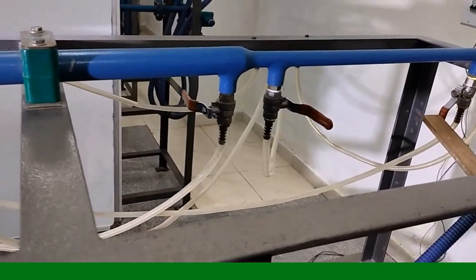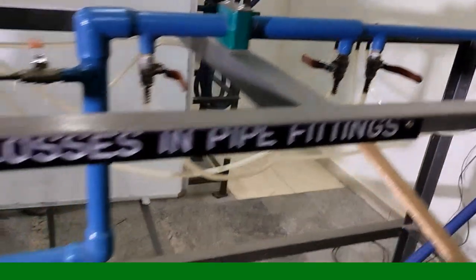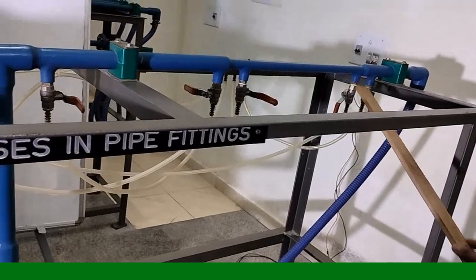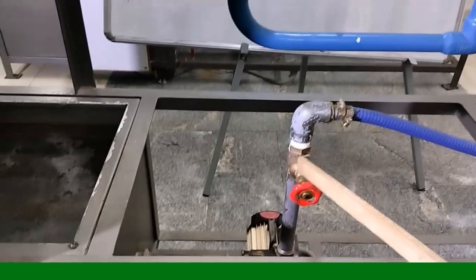Once this ball valve or pressure tapping valve is opened and the pump is on, for different flow rates we have to take different readings. For one flow rate, you collect the pressure measurement from this U-tube manometer.